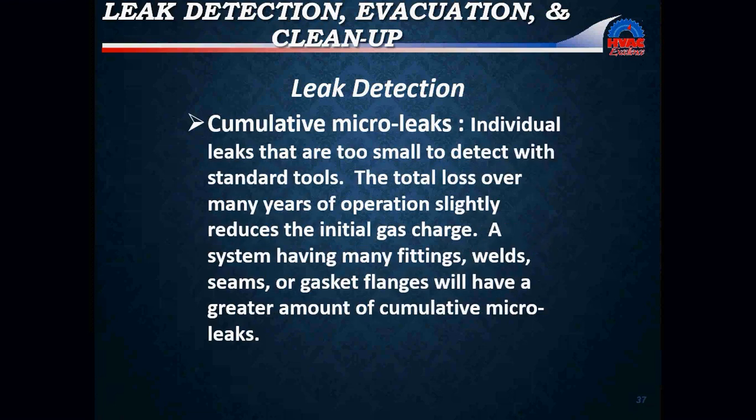So now, with leak detection, we have cumulative micro leaks. Individual leaks that are too small to detect with standard tools. The total loss over many years of operation slightly reduces the initial gas charge. A system having many fittings, welds, seams, or gasket flanges will have a greater amount of cumulative micro leaks.